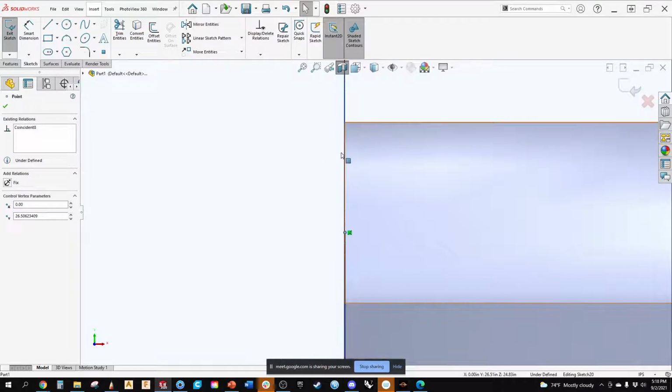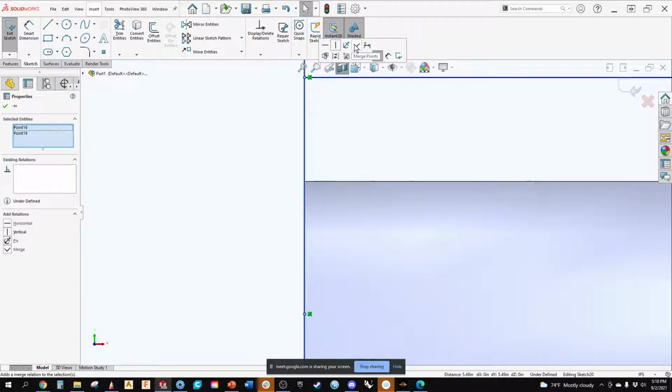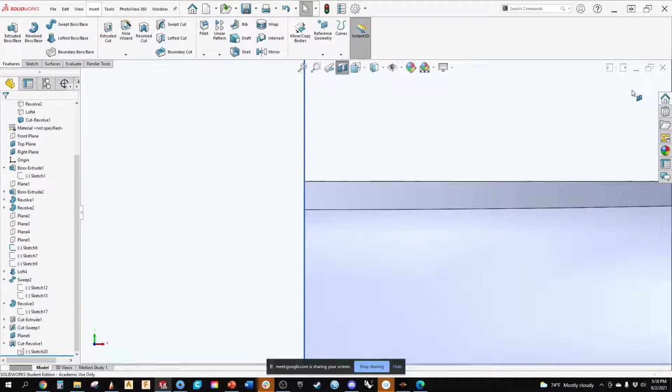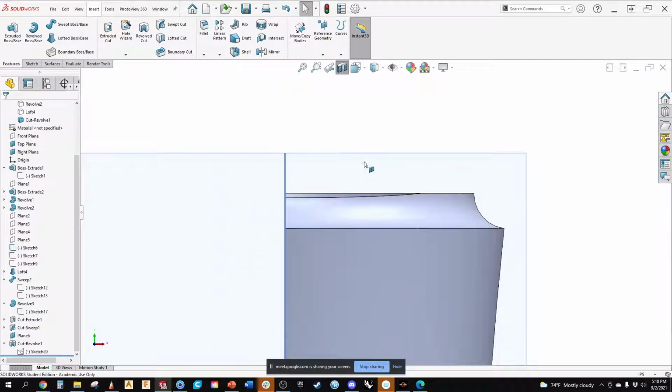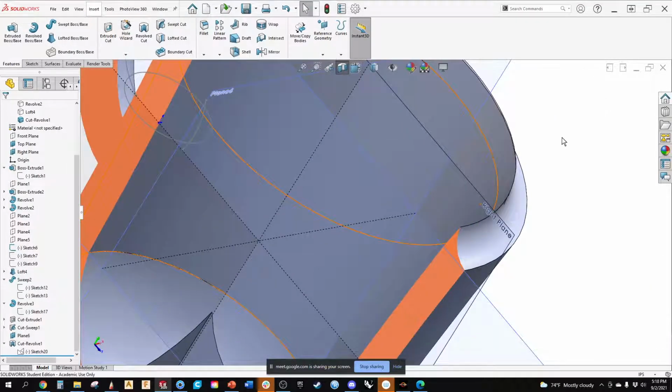It needs to be closed off up to there. So usually, whenever I try to do a sketch and it doesn't want to finish the command, the first thing I do is go to make sure that my sketch is closed loop and look for those dots. So there, now we've created our shape.